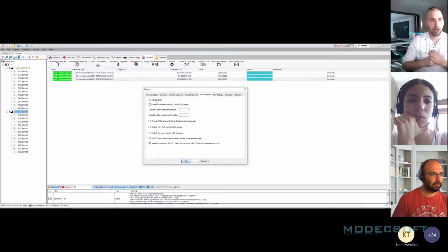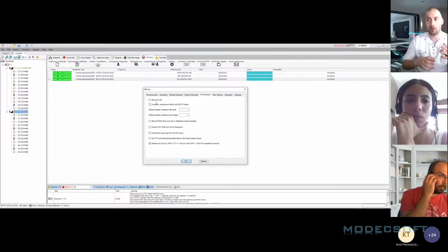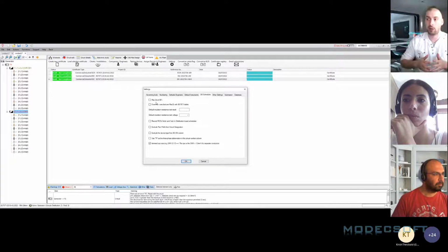However, within the software, we are already calculating for things like C minimum, C maximum values, so for our voltage differences on our system, and we are also taking into account, if you've designed the system when you're doing the test inspection, specific cable ratings, operating temperature of the cable under that particular load or its maximum load that you're expecting on that cable. So the reasons why the 80% was there to begin with, we can mitigate in other areas, particularly if you're undertaking that design as part of that element.